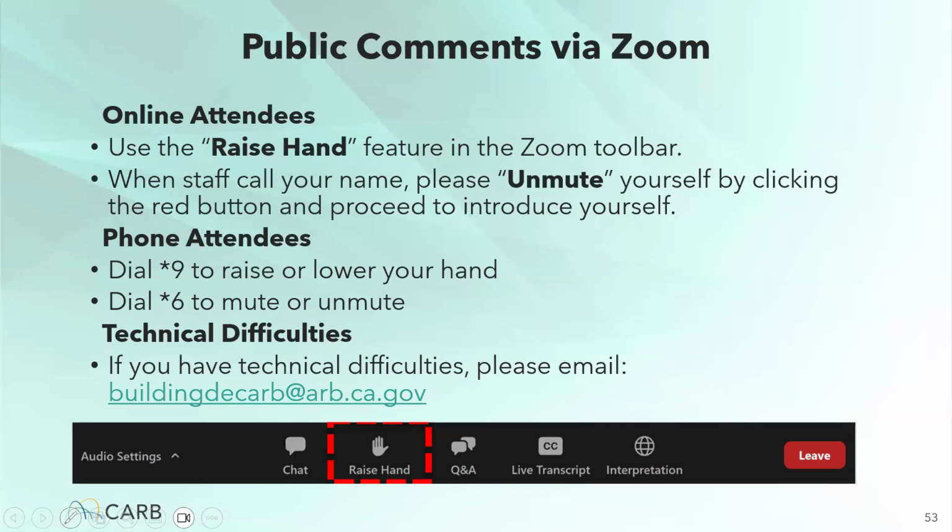Thanks, Sam. Next question here from Omar Gutierrez Tapia. Do the electrical capacity retrofit levels consider other fuel substitution end uses such as cooktops and dryers? And I'll pass things to Allison Hyatt. Yeah, thanks for this question, Omar. So for the residential analysis, the panel capacity thresholds could accommodate all end uses, but they may need panel optimization if between 100 and 200 amps. For the non-residential analysis, we only considered electrical impacts from space and water heating at this time.